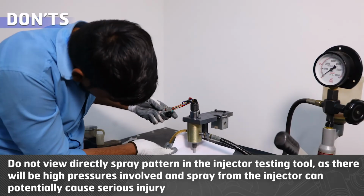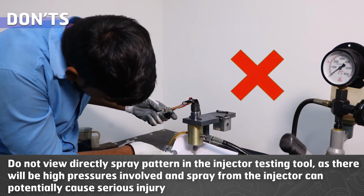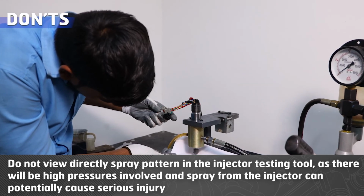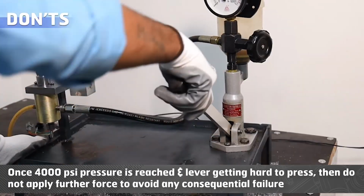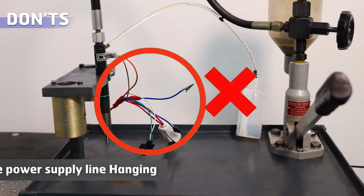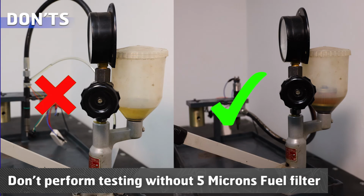Don'ts: do not view directly spray pattern in the injector testing tool, as there will be high pressures involved and spray from the injector can potentially cause serious injury. Once 4000 psi pressure is reached and lever is getting hard to press, then do not apply further force to avoid any consequential failure. Don't leave power supply line hanging. Don't perform testing without 5 micron fuel filter.